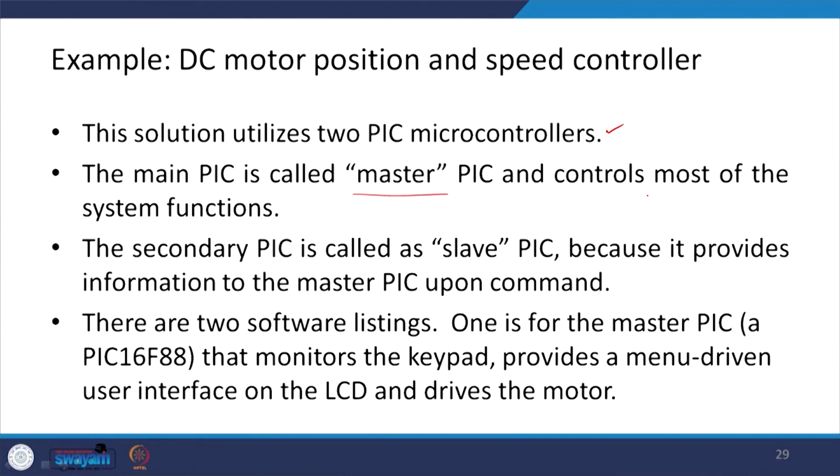Now, this solution utilizes, say, 2 PIC microcontrollers. The main PIC is called the master PIC and controls most of the system functions, and the secondary PIC is called the slave PIC because it provides information to the master PIC upon command. There are 2 software listings. One is for the master PIC that monitors the keypad, provides a menu driven user interface on the LCD, and drives the motors.